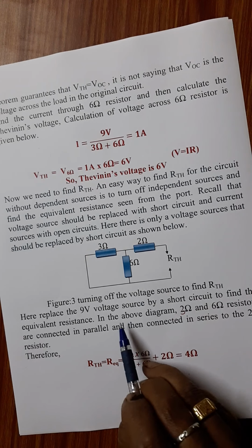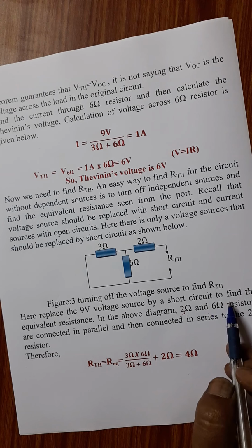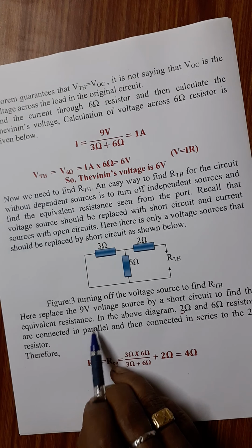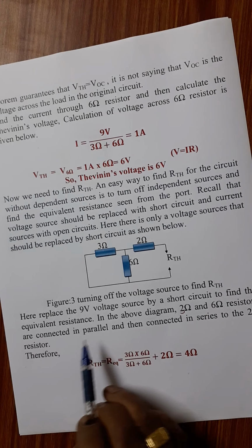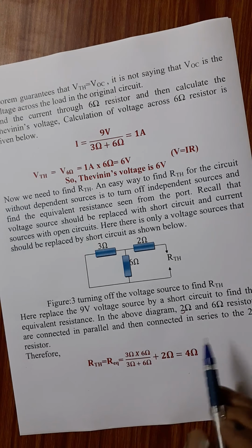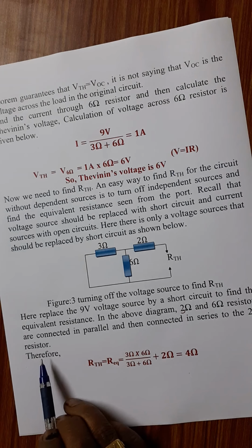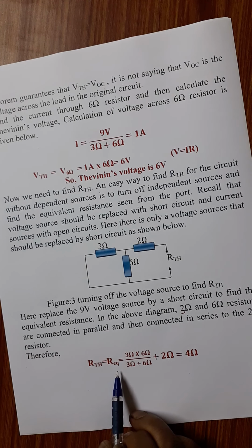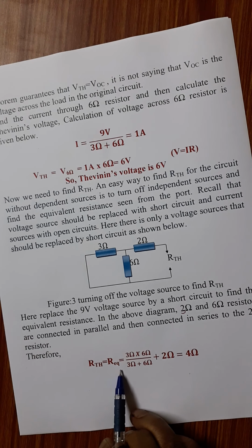So replace the 9 volt voltage source by a short circuit to find the equivalent resistance. In our diagram, the 3 ohm and 6 ohm resistors are connected in parallel and then in series to the 2 ohm resistor. So the RTH, or you can call it the equivalent resistance,